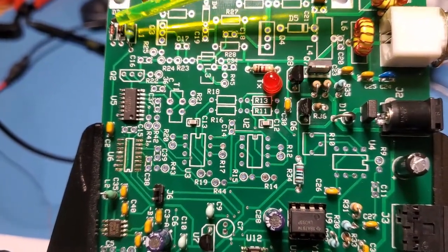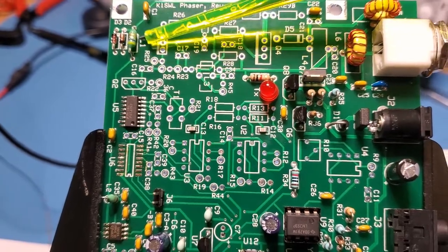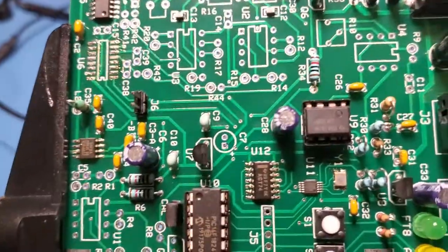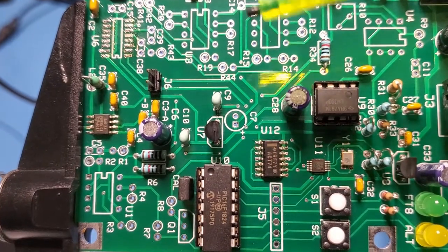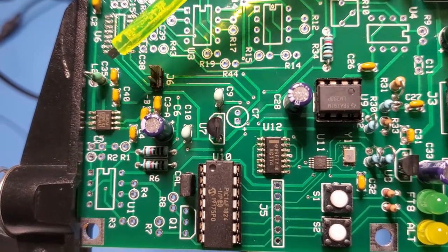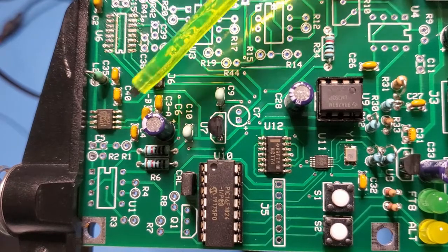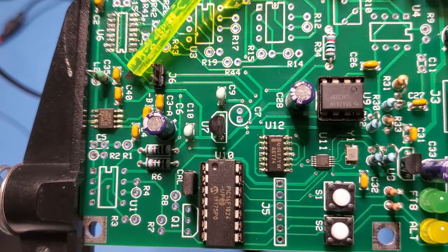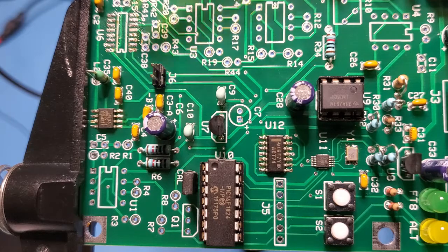So just a quick update. The two clipping diodes have been installed up here together with this inductor and this capacitor, and then moving down closer to the SA602, all the capacitors associated with it are installed. One little note, and it is covered in the errata in the manual: this is actually C46, a filter cap on pin 8, which is the power supply for the NE602.